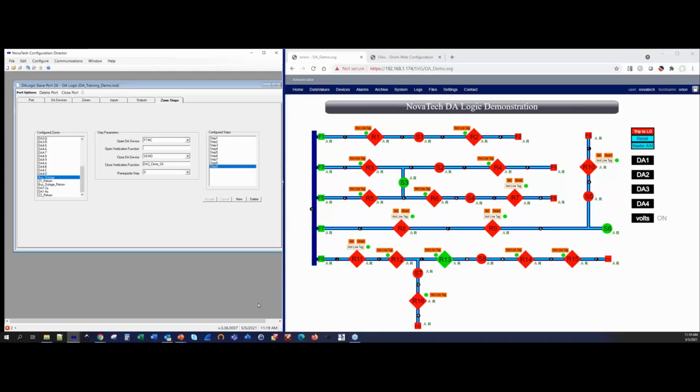I personally feel that you should be cautious in doing any kind of automatic restoration from DA, and my reasoning for that is that typically DA is going to operate after an outage for something bad on the system. You know, a storm has come through, poles are broken, trees have fallen down, whatever the reason is.